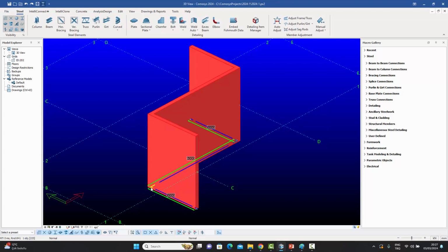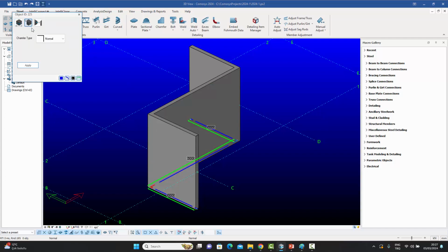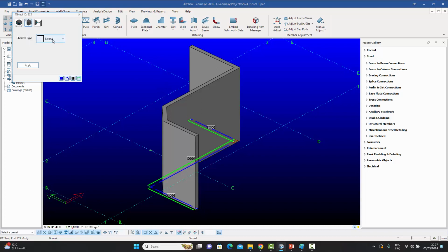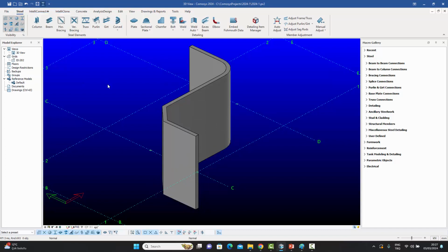And you can just go and select that chamfer for the second point and just say that I want to give this a chamfer, this type, and you just give those parameters. So you don't need to remember which point was which, which made it a bit difficult. You can just go like that. Similarly, you can go and select the other chamfer, enter that, give it another chamfer variable, for example, and it's much easier like this on the screen.